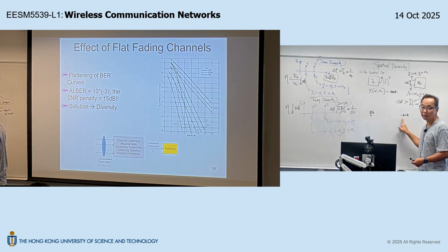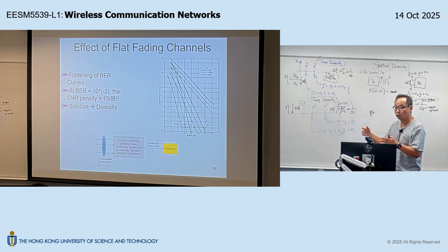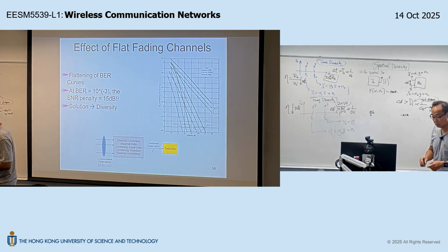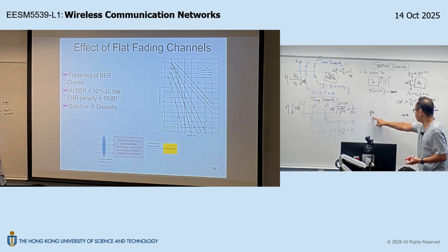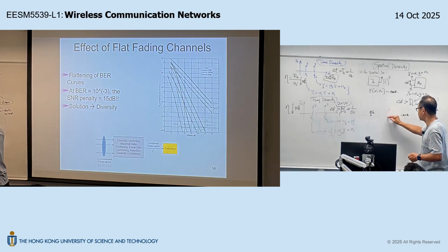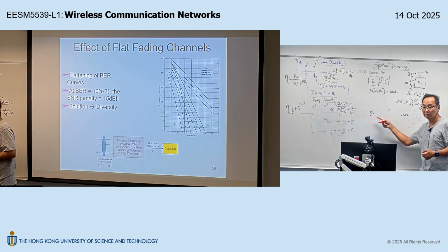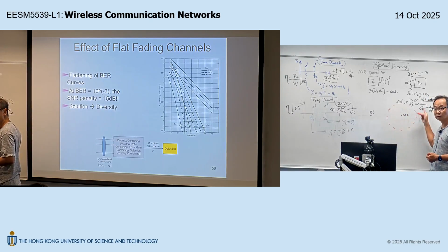On the other hand, the mobile receiver is at the ground level, low elevation. If you look around, you don't see the base station, but you see scattering clusters surrounding the mobile station, right? So in between the base station and the mobile station, there is some scattering cluster, like this, okay? So that's why you don't see the base station directly. You see the scattering clusters.